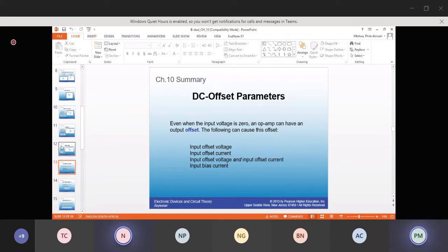So that covers the main categories of circuits that you look at: the inverting amplifier, the non-inverting amplifier, the summing amplifier, your integrator, your differentiator, and the unity follower. With a unity follower, whatever you put in comes out as it is, unless that signal is connected to an inverting input. It will come out as it is, but 180 degrees out of phase with your input. That's what negative denotes.